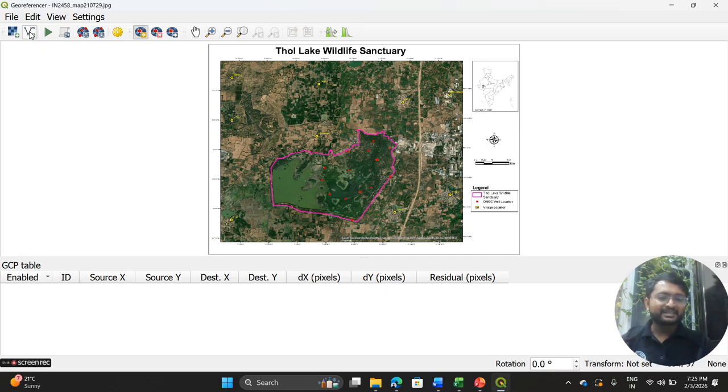image. Or you have taken an image and you don't know that it is not georeferenced, and you started tracing and already saved the file. When you open this file again with some other data, you see that this GIS data is not overlapping with my data. So this is the issue while creation. The person responsible for creating the vector data made some mistakes, and because of that the layer is not properly georeferenced.